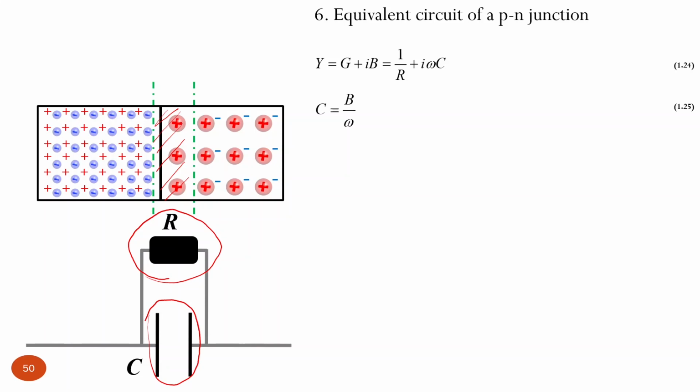And so-called admittance, which is the reverse of impedance. Impedance is the total opposition of an electric circuit to AC current. So admittance is 1 over impedance, but we will show it again. It consists of real and imaginary components. So we have conductance and susceptance.